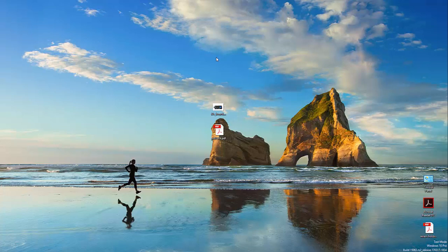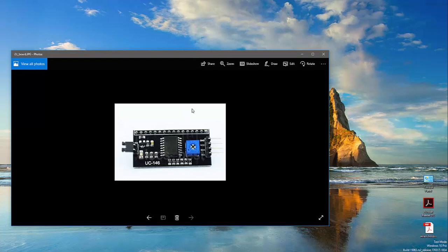Hi, this one will be about I2C. I will try to make it as simple as I can. So first we will start with this board that is on sale on eBay and other locations on the internet and is used for Arduino, for example Arduino LCD. What it is doing, actually, is converting the I2C into control of 8 bits and using this message in order to control LCD and other stuff.